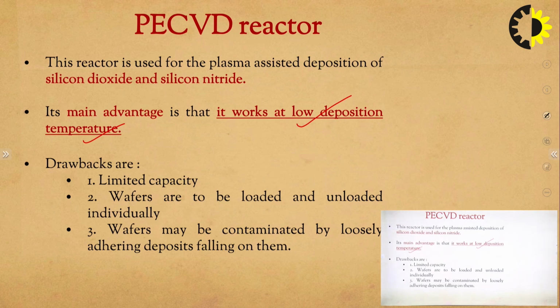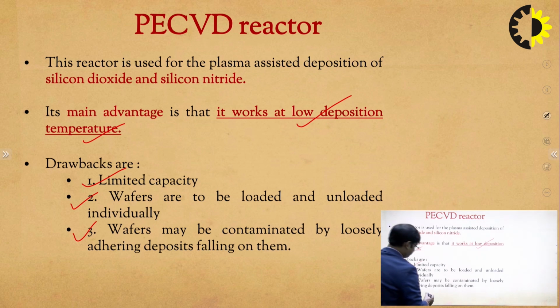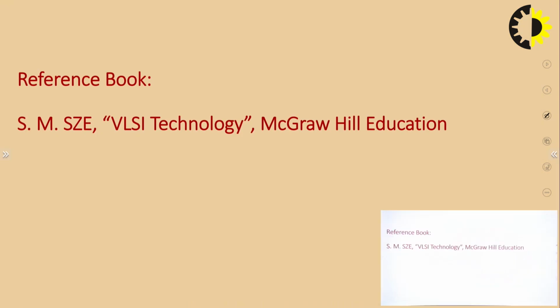But some of the drawbacks of plasma enhanced CVD are limited capacity, wafers have to be loaded and unloaded individually, and wafers may be contaminated by loosely adhering deposits falling on them. So, these are some of the drawbacks of plasma enhanced CVD.